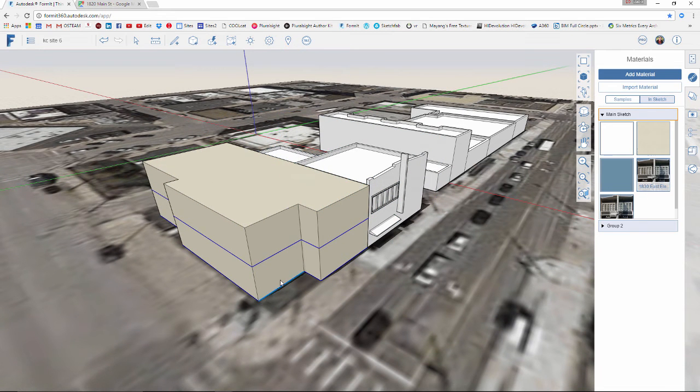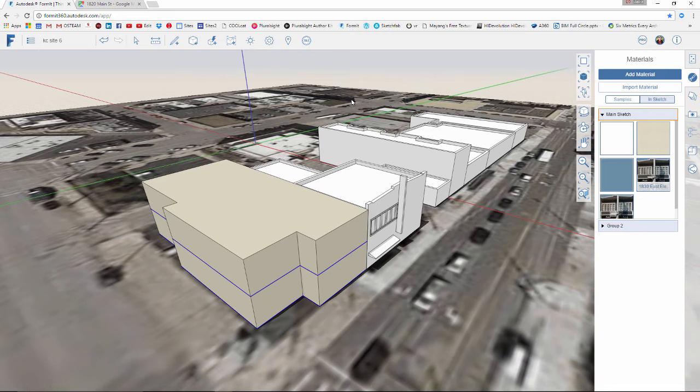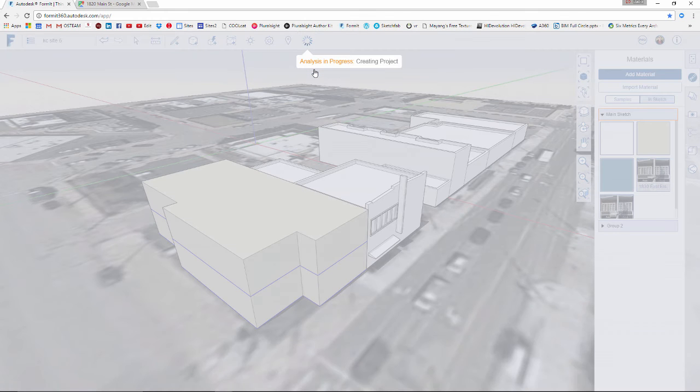And now we have levels established, so we should be ready to run our energy simulation. So again, I'm going to click the 19.1 energy cost button and generate insight. This will take a few minutes. Essentially, this is calculated in the cloud, and it's going to go through a process where it's converting the geometry to run the simulation. And as soon as that simulation is done, it will send me a note back, so I can begin observing what the results are on that energy simulation.